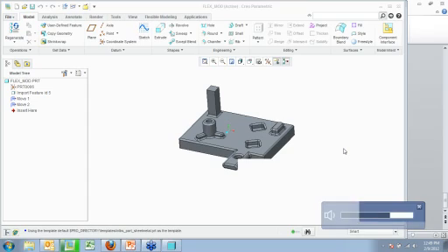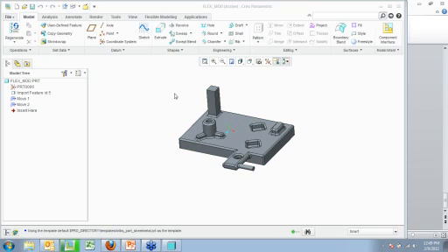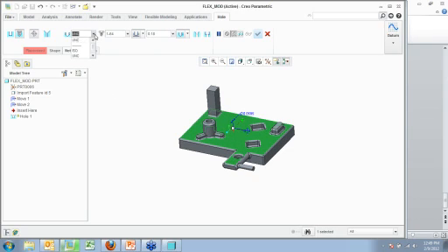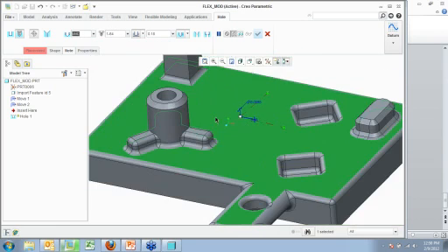He typed it in: does Creo Parametric offer a threading profiling tool, i.e. the ability to cut threads? That's the same as it was in Wildfire 5 and I believe Wildfire 4 and maybe even Wildfire 3. If I want to come in here and create a hole and put cosmetic threads on it, I've got my UNC and UNF and ISO, and I think you can even add NPT tapered threads. We used a lot of pipe threads at my last job. I can't remember if that was a custom thing we made or something we downloaded. And it'll create cosmetic threads.